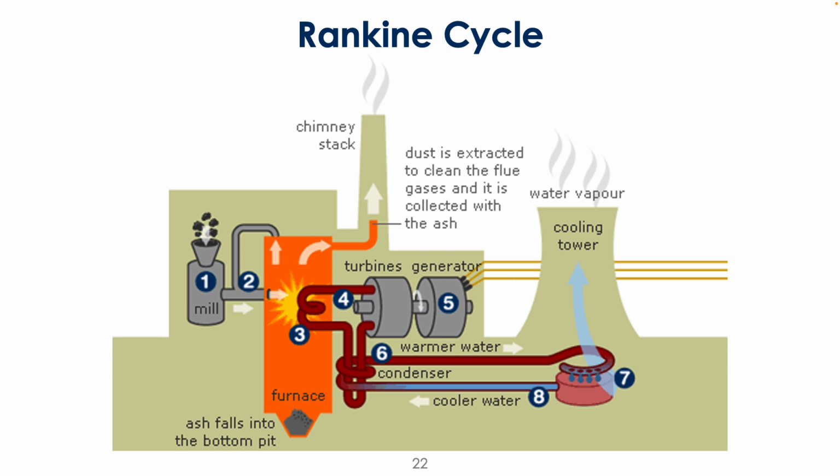Okay, and so if you see pictures of these coal plants, you'll see both cooling towers and these larger chimney stacks. And the other reason why they're really tall is that when pollution gets emitted, it disperses and diffuses, and so by the time it reaches ground level, it has to be at certain concentrations. You have to keep it high enough that once it reaches ground level, it's at that regulatory required concentration.